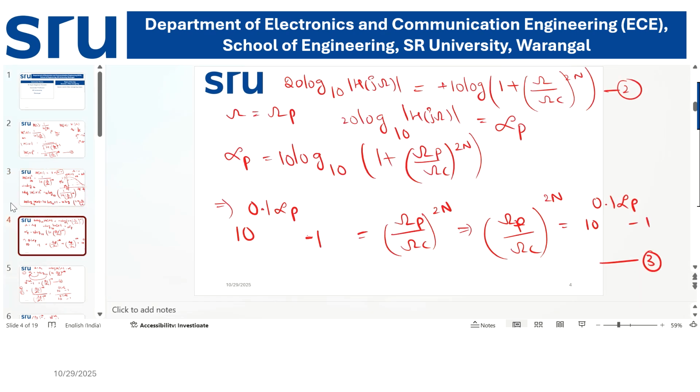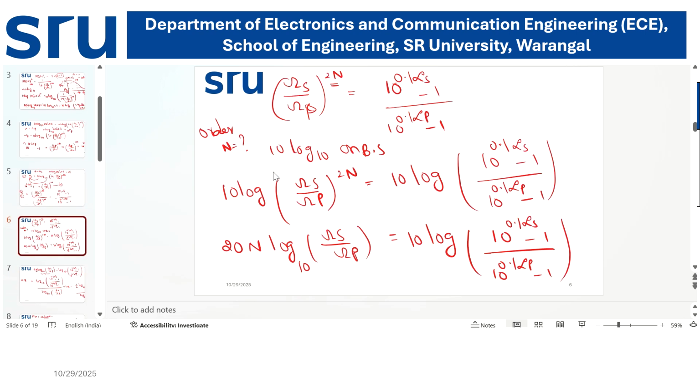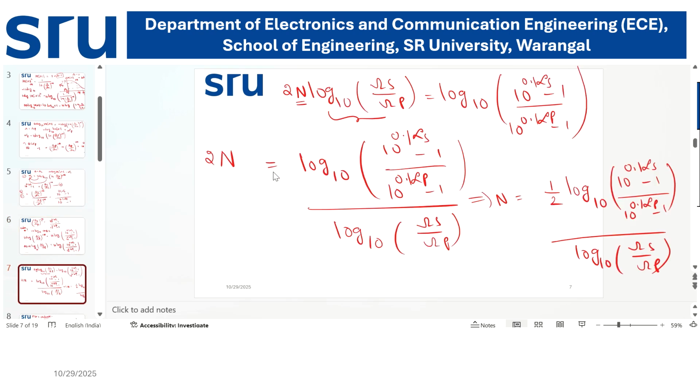If it is 0, the gain is maximum, 1. If it is omega p, we considered the characteristics in terms of dB as the passband attenuation. So we got equation number 3. Next we substituted the passband and stopband edge frequencies and stopband attenuation, and divided these two so that we can find the order of the filter. Therefore we got the order of the filter as three different formulas.